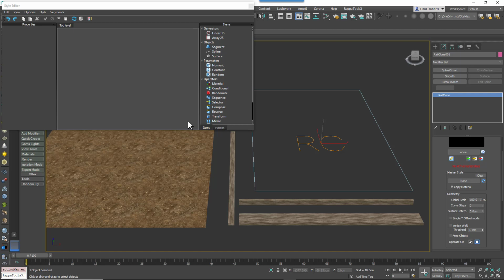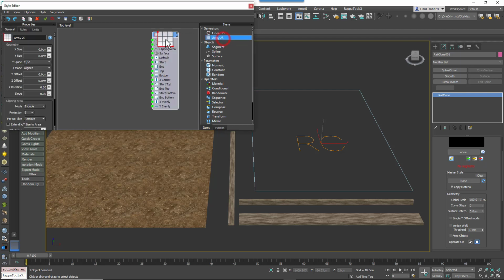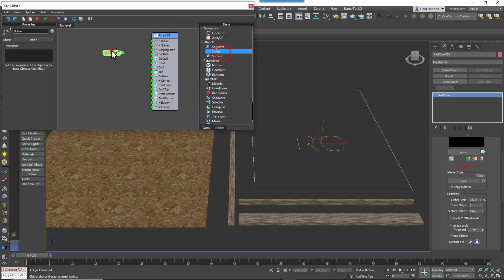In this case we're going to use 3 generators. We're going to use 1 just for the planks, 1 just for the stakes, and a third one to add the soil on top as a kind of lid. So we'll start with the boards. Create a new A2S generator. Create a spline node and wire it to the generator's spline input. Select the closed spline from the scene.